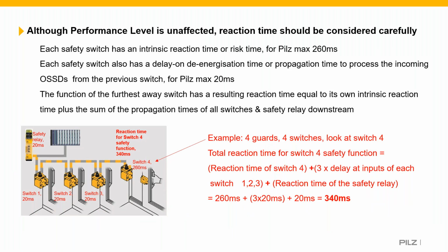One other point that I will mention just to consider is that if you have multiple switches connected in series, you do need to consider the reaction time of the whole system. So, for example, here we've got a system with a safety relay and 4 devices connected to it. Because of the delay between each switch and the cables going through and the reaction time of the safety relay, here we could have a worst case scenario of a reaction time of 340 milliseconds. So again, that needs to be taken into consideration on what is the safety distance that we need to have for where the guard is away from the hazard point.